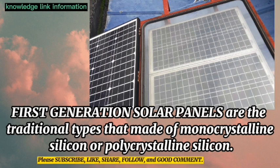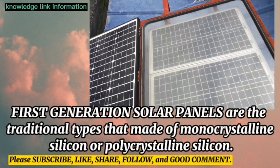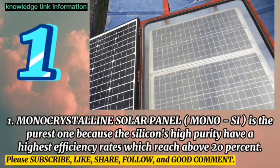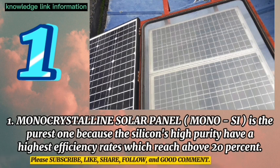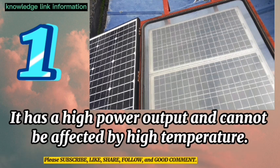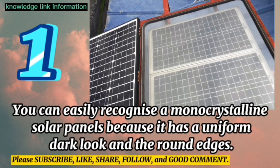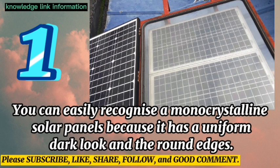First generation solar panels are traditional types that are made of monocrystalline silicon or polycrystalline silicon. Number 1. Monocrystalline solar panel. Mono Si is the purest one because the silicon's high purity gives the highest efficiency rates, which reach above 20%. It has a high power output and cannot be affected by high temperature. You can easily recognize monocrystalline solar panels because they have a uniform dark look and rounded edges.